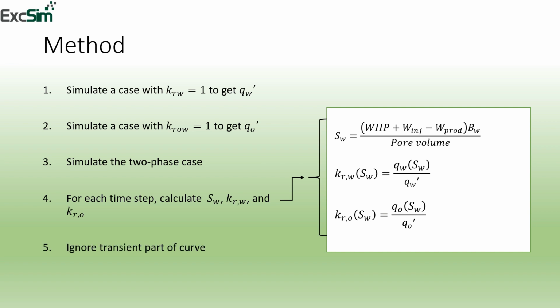Typically, in using this model, the first few time steps will be in a transient mode. It will not be a pseudo steady state condition. So you're going to have to ignore the first steps.